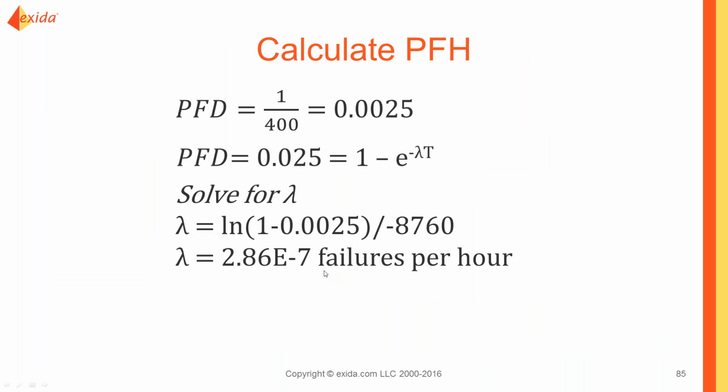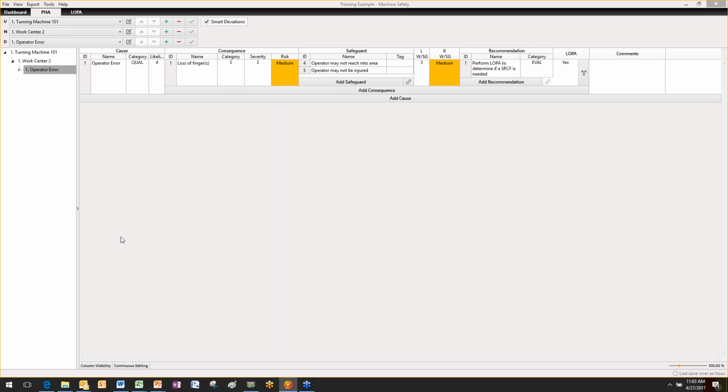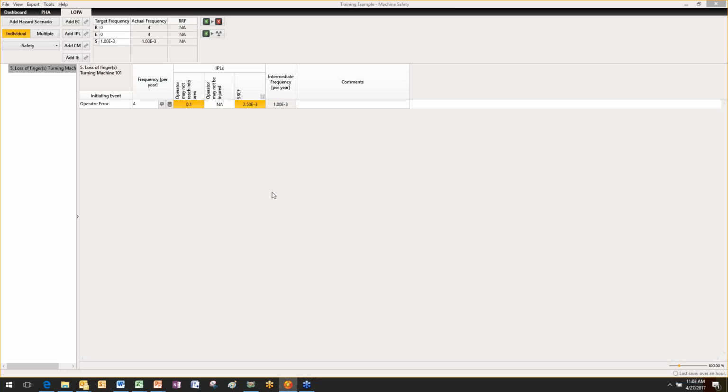So that would work into this technique, with the way we set up our tolerable risk giving us a similar answer. But one benefit of the LOPA is there may be more than 2 or 3 layers of protection you could potentially claim, and then you could clearly articulate them and document them in a LOPA approach. Now there are tools that can help do that. So there's process hazard analysis tools that we could document and do our entire machine analysis or machine risk assessment on, and we can do our LOPA where we're entering the data and the tool is calculating and tracking all those potential safeguards we need to have.